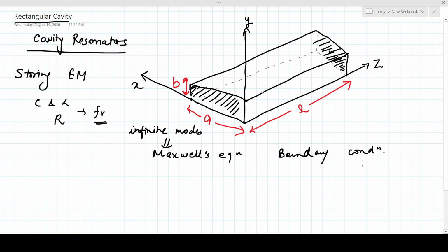to the appropriate configuration. When the frequency of the impressed signal, let's say F, is equal to the resonant frequency of a particular mode, then the standing wave pattern that would have appeared due to reflection through the walls has maximum amplitude, and the peak values of stored electric energy and magnetic energy become equal.